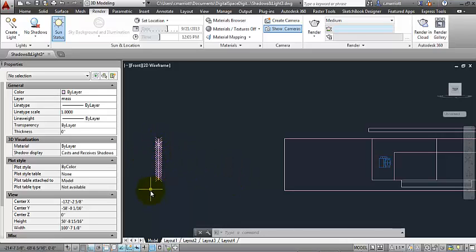All right, so I have my riser heights, but how do I determine what the treads should be? So what I'll do is, again, I'll use my calculator tool, and I want to know exactly what my risers are. So I'm going to type in this time 144 divided by 21, since I chose 21 as my number of risers. And I get a value of 6.85. That will be my riser height.